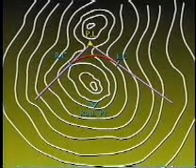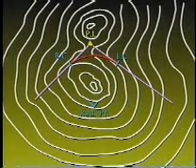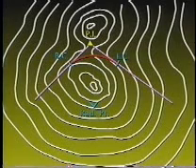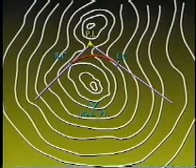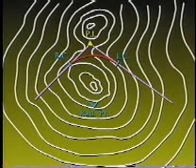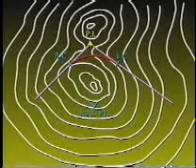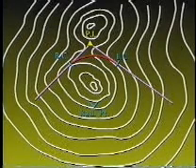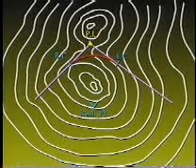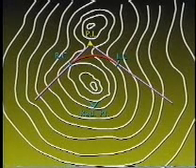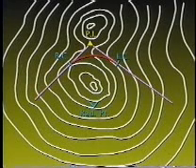Next, horizontal curves are designed to provide a transition for each change in direction. Design considerations such as sight distance and speed of travel determine the selection of radius length for the curve. Using the mathematics of circular curves, which Ed is going to discuss, the length between the PI and the beginning and end of the curve, that is the BC and EC of the curve, and the distance along the curve can be determined. With this information, stationing can be calculated along the curve.